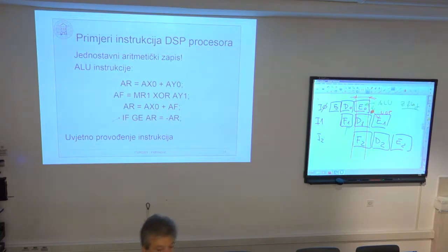So the idea is to have an assembly level preprocessor that takes care of all of these potential stalls. So it will automatically insert no operation where it's needed. When it knows exactly that this argument is needed in the next instruction and it is not available, because the depth of the pipeline is not the same for all of the instructions, then it must synchronize by adding a NOP operation in between.